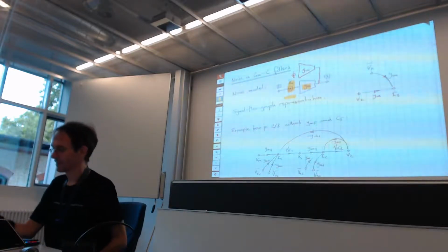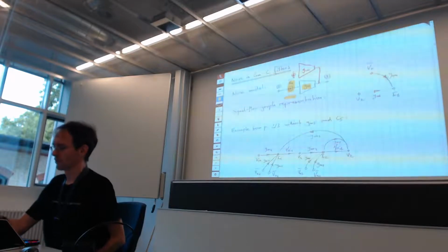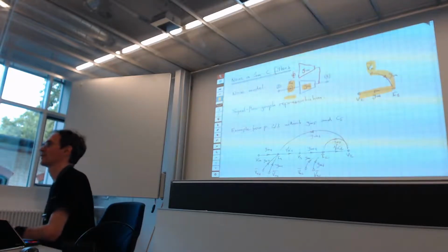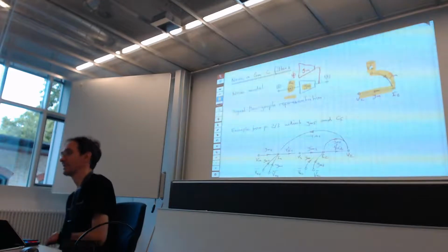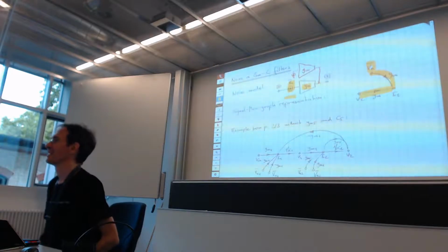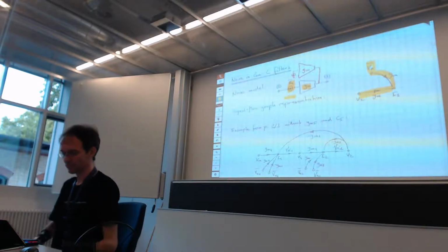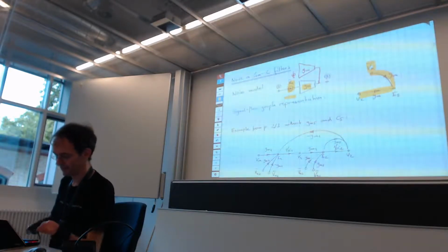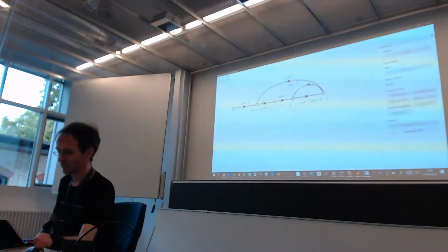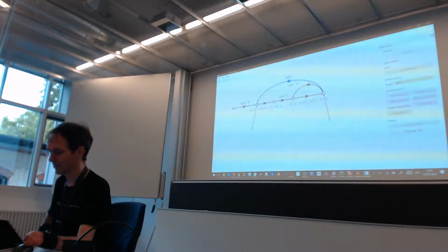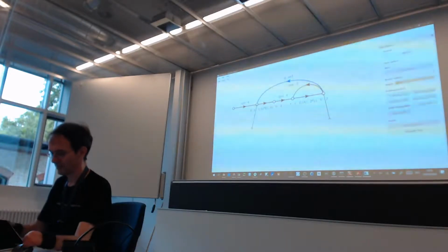But we have a big advantage with the signal flow graph, don't we? From the input referred noise voltage, if this is the signal path, we just can add another branch which goes to the same point as the GM with the same weight as the GM. And the input there is the input referred voltage. So if you have that, then you can now extend the input referred voltage of that circuit. Here I have a GM1, a GM2, a GM3, and a GM4.